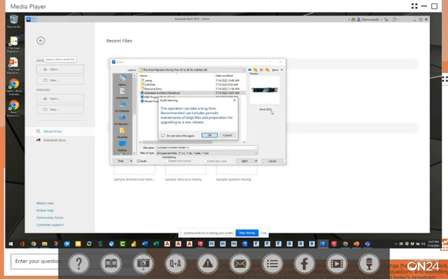Here's the thing, if you guys are taking notes, here's a best practice. You never skip more than 2 versions of Revit in a file. So if you're downloading families or content from your manufacturers and they're in old school Revit 2012, 2015, the program has changed so much in the background that a lot of the programming, the language, is completely different.